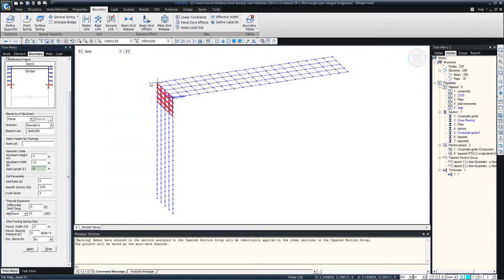So I'll switch to the view. You can see most of the places you can measure the distances directly from the graphical user interface. Void ratio, this is something you get from the soil data. Cycle factor, this is the factor that considers the fatigue. I will show you the basis for this, the empirical formulas required for this. Thermal expansion to be considered, say 20 degrees, and the material of the abutments, piles, and apply.